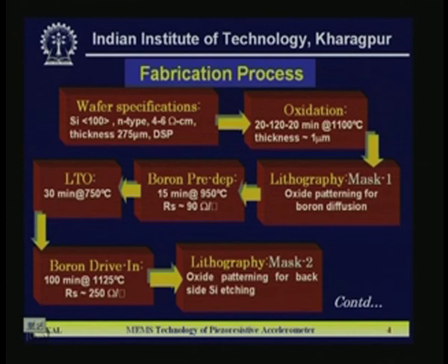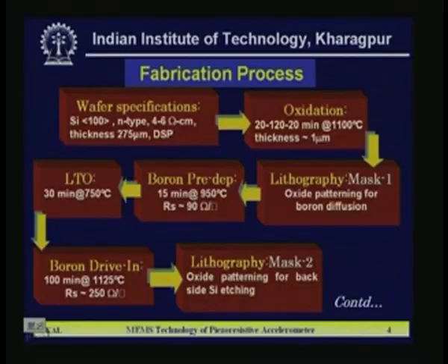We use this because we have to remove some boron stain. During the pre-deposition diffusion, using the boron source, boron nitride cake, a boron stain, that is borosilicate glass, a very thin layer of borosilicate glass will be deposited along with pre-deposition diffusion. This thin layer of borosilicate glass is very difficult to remove afterwards, means after drive-in, and in drive-in we know